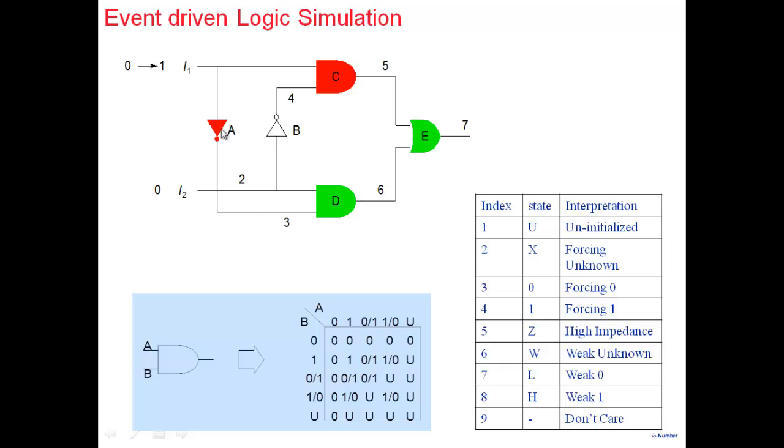We also know that we would like our circuit to run at certain speeds. For example, this is simply a combinational circuit, but I could have a flip-flop here, and I1 and I2 could also be coming from a flip-flop. And so I would like to know what is the highest clock frequency that I can run. And for that, I need to know what is the slowest path in this particular circuit. So in order to decide at what clock I can operate my circuit, I need to know the delays in my circuit. And delay estimation using logic simulation is very time consuming.